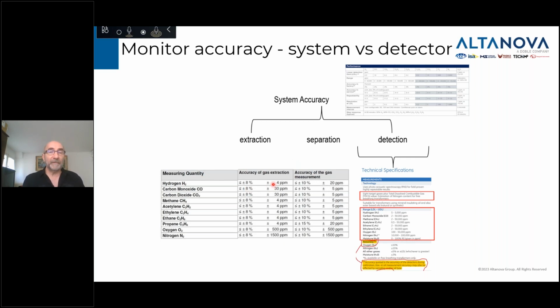So specifically, when you write a spec like that, what it means is that, let's say for hydrogen, your accuracy now is 18%. And if you're looking at the fault gases, especially the gases used in all the different diagnostic tools I showed earlier, the methane, the acetylene, the ethylene, and ethane, together, the accuracy of that system, brand new equipment starting at the beginning, has an accuracy right away of 18%.